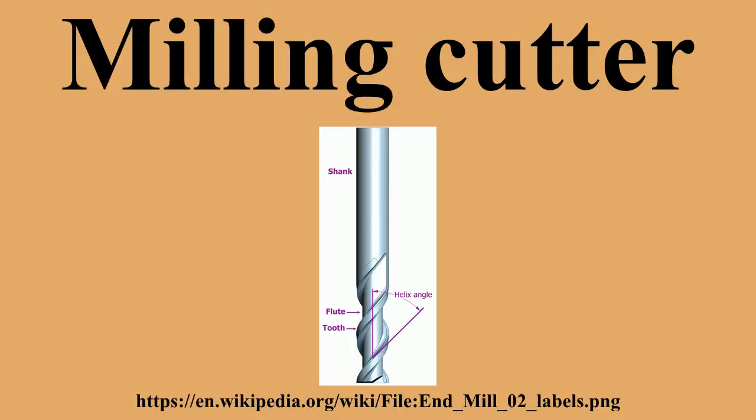Often these bits will be mounted at right angles to the bar's main axis, and the cutting geometry is supplied by using a standard right-hand turning tool. Regular fly cutters are widely sold in machinists' tooling catalogs. Fly bars are rarely sold commercially; they are usually made by the user.